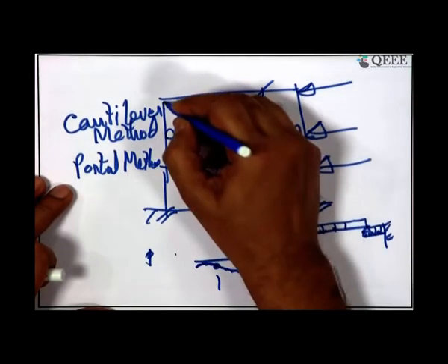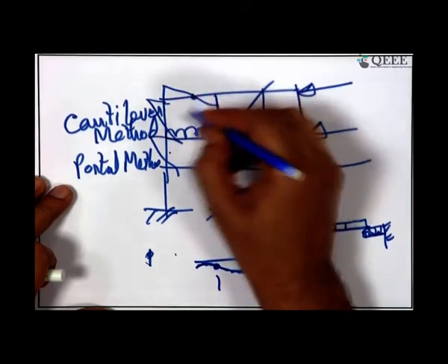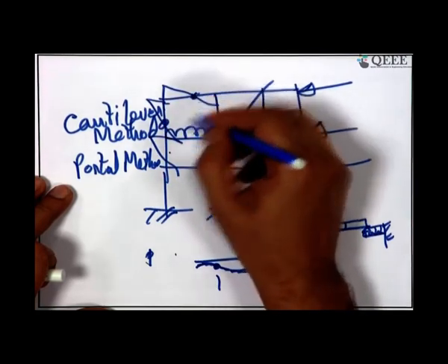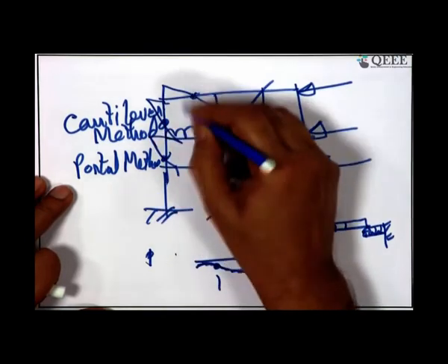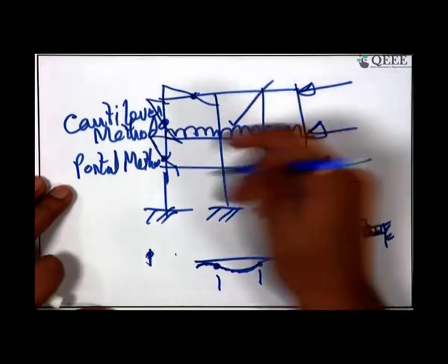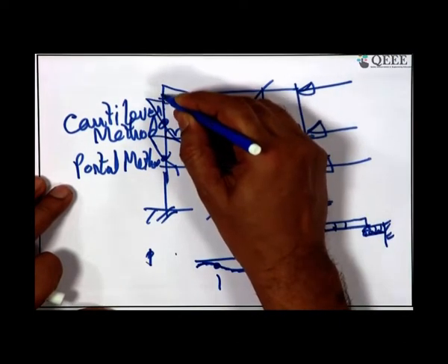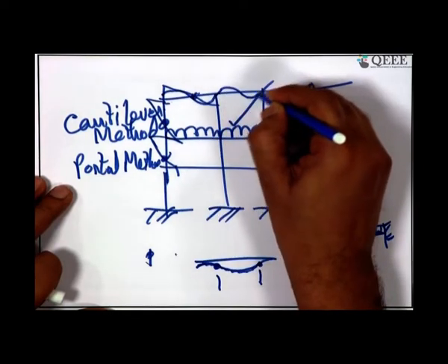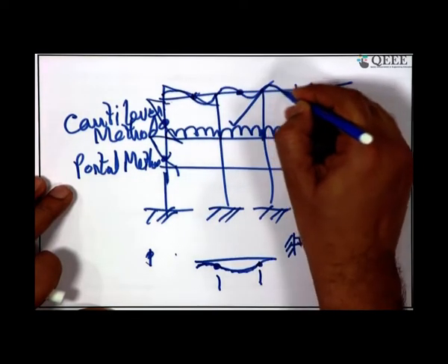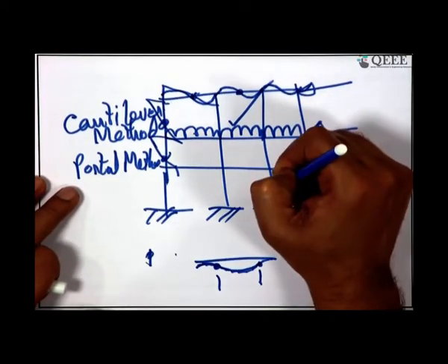But mind that there will be assumptions that the inflection points occur at the midpoints or somewhere else you define, and like that you can have a linear variation of the approximate bending moment. Really, the bending moment will have a moment here, a curvature, and then an inflection point in the middle. Like that you can draw the bending moment diagram and the shear force diagram.